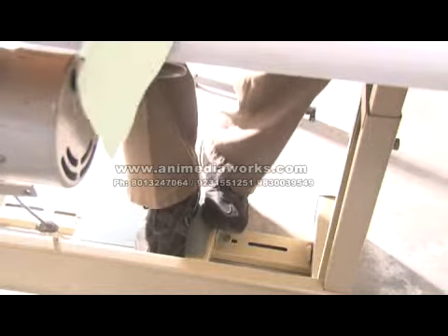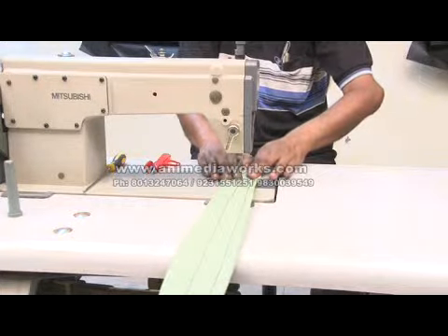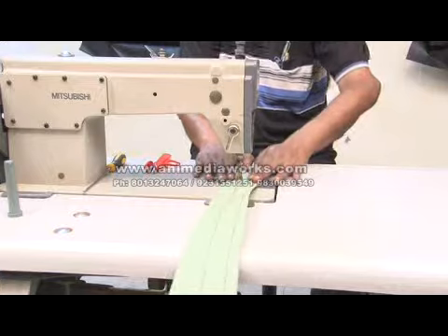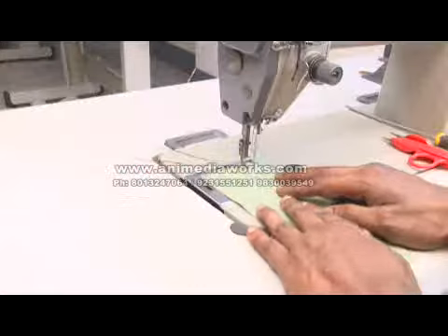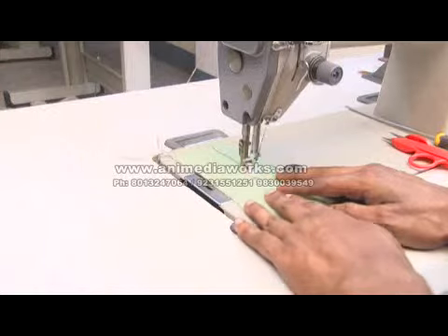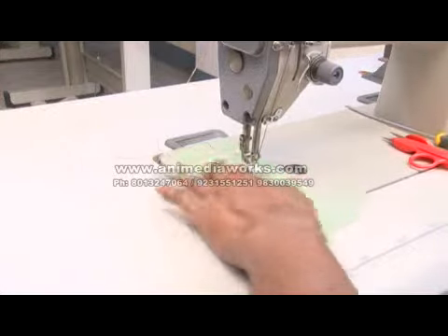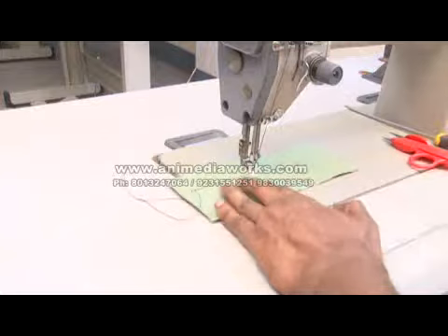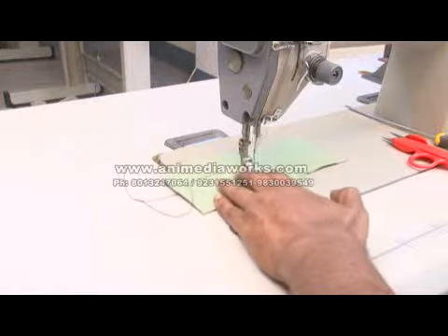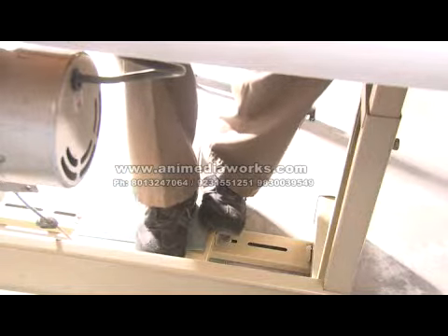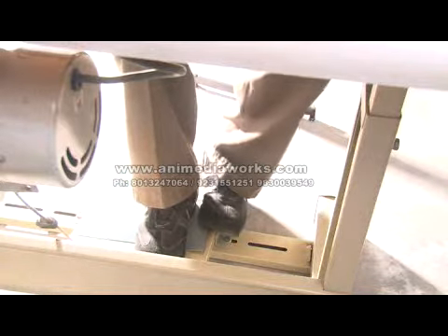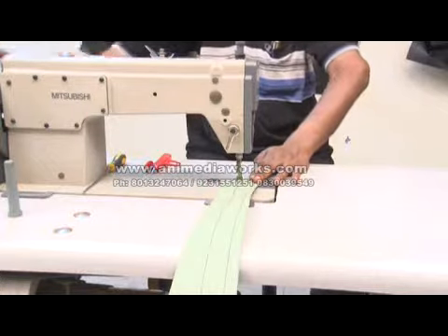The machine will advance the material automatically. The operator needs to guide the leather through the straight lines and curves. For a sharp corner, stitch to the point where it has to turn, leave the needle piercing the material and change the direction of the material by lifting the pressure foot. Release the pressure on the foot pedal to bring the machine to a complete halt.